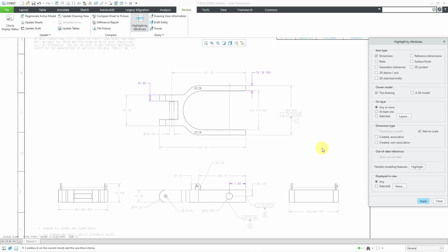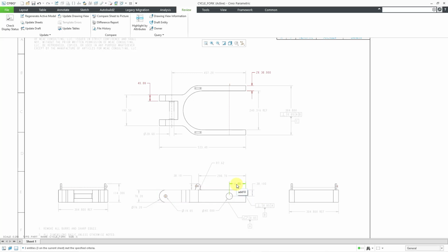One other thing that I want to mention is that this dimension here has the symbolic form ADD followed by a number. But this other one that is associated with that sketched in circle has DD followed by a number. Same with this one over here. Just to make different things show up in different colors, halfway through preparing this drawing, I changed a drawing detail option.